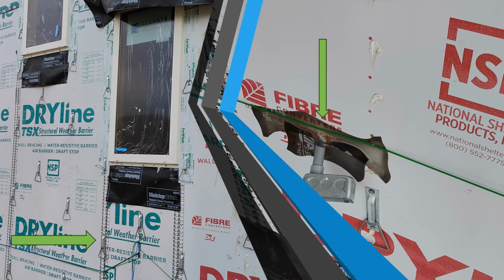It's closing off any air gaps that are in there. In my opinion, this type of sealing tape meets the intent of code requirements, saying that it must allow for expansion and contraction while maintaining a tight seal and bond for both materials. Poly seal and expandable foam really do not. It will fill the hole, but once it expands and contracts, it will pop and allow air leakage around those areas.